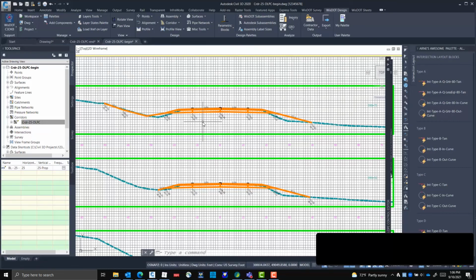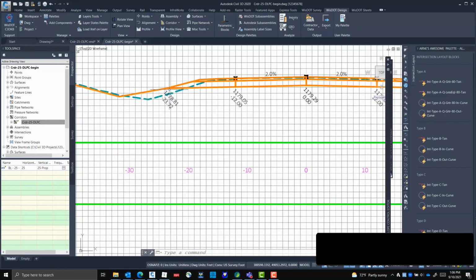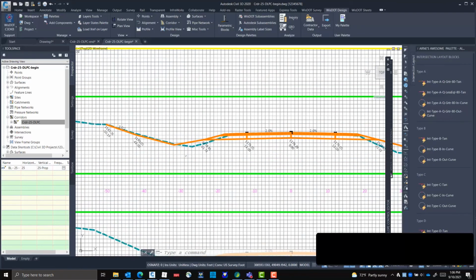Boom. Ditch. Okay. Even though we're landing the subgrade shoulder point above existing ground, we can force a ditch. And it's got all the controls to be able to drive your ditch elevation to custom levels. You can do a flat bottom ditch. There's a whole topic linked in the notes on a deep dive on getting into all the nitty-gritty. But what I want to show you is being able to do this.